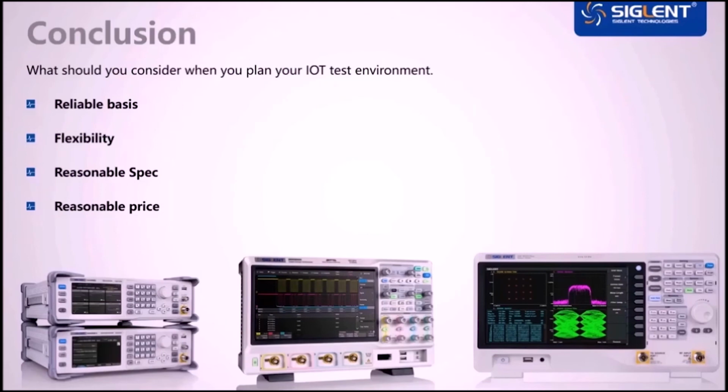Often, you can buy automated measurements for your devices afterwards, like the standard communication test which I mentioned before. With our devices you can even buy additional features like a VNA, but the bandwidth or the noise floor is determined by the hardware. That's why you should make sure that you have the bandwidth and the dynamics that you need. There's of course another factor at this point. The price has to be right.